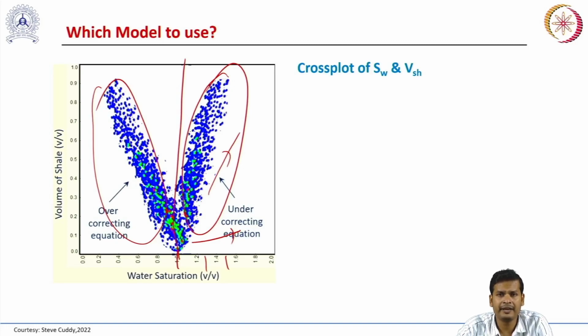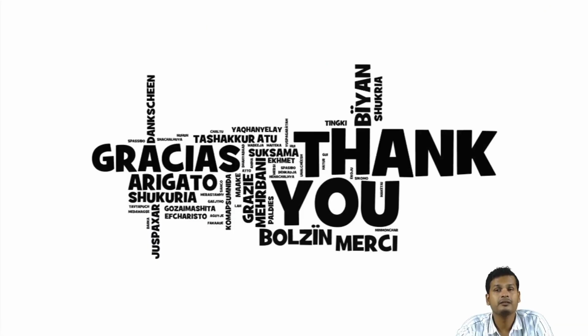So before using any of the water saturation models, first check what the model is based on, what the hypothesis of this model is, and in what conditions it could work. Then only use a particular model to calculate the water saturation in your shaly sand reservoir. So this is about shaly sand analysis.